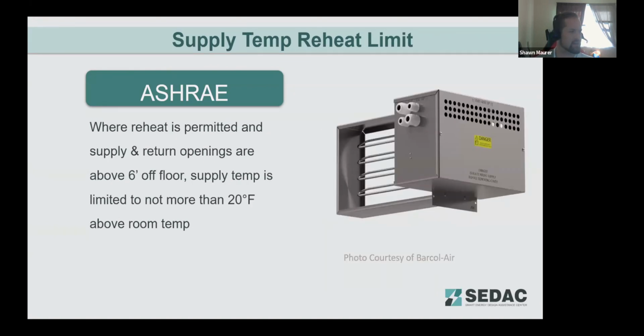We'll check and verify that for larger multiple unit bathrooms, whether that's an applicable thing that can be done if you're controlling both the supply and exhaust and balancing that. I wouldn't recommend it though, as you can still get odors building up in that space.